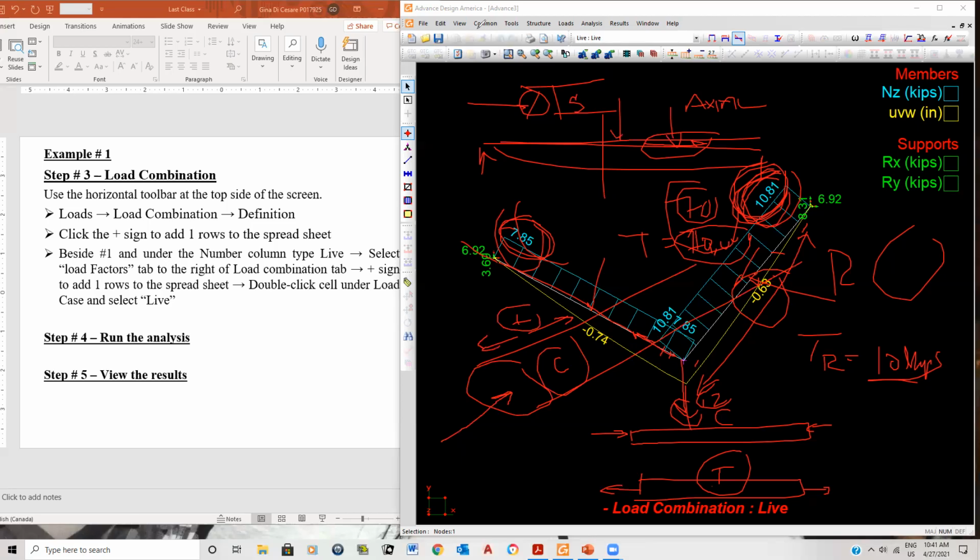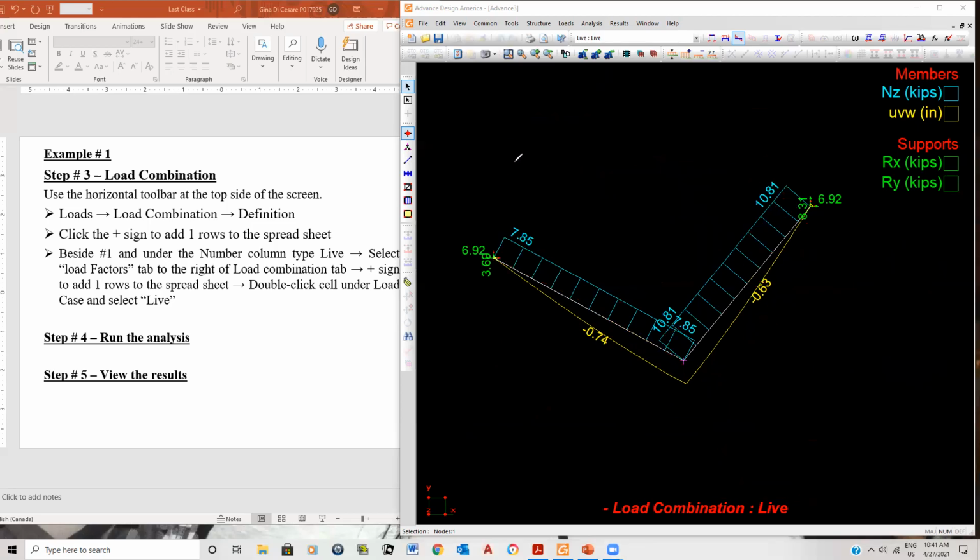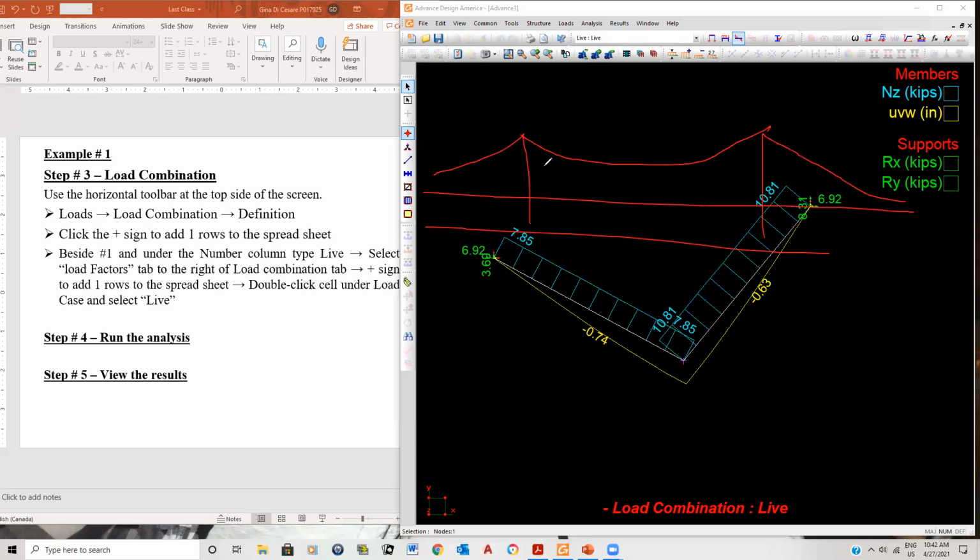And just for your general information, the nice thing about designing a suspended bridge, when you have your cables here, is that it was made with steel cables, and here's, of course, your steel deck. The beauty of this is that the whole top cable of the suspended bridge was all in tension, and not only that, all the hangers they used to support the bridge deck were also all in tension. So that was the best way.